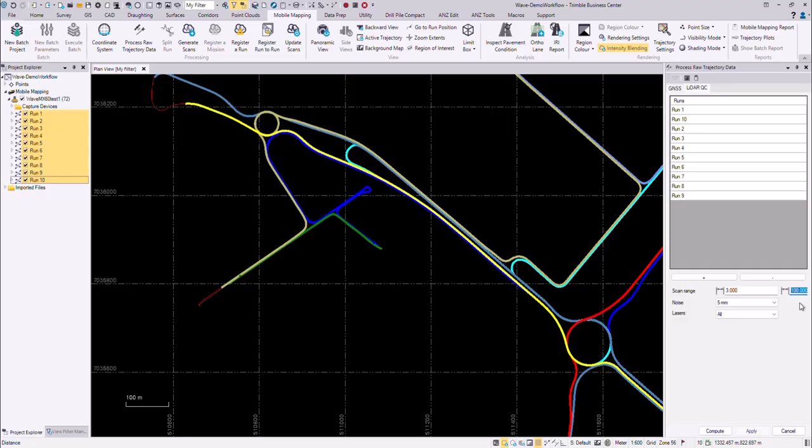So I know within, say, 40 meters of the scan head, and I'll probably leave the minimum at 3, within 3 to 40 meters of the scan head is going to be the most accurate scan that can help back process the trajectory. Just like in a SLAM environment, you don't want a SLAM position to be processed off something 100 meters away. You're introducing noise into that processing and reducing the quality.